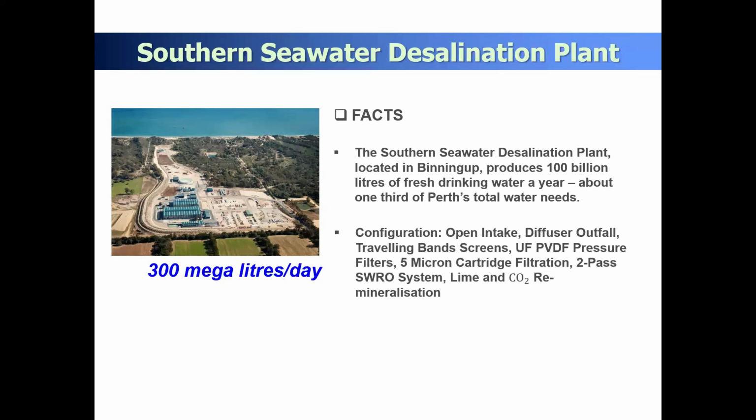Depending on what they like to do, they have different media, like natural sand, and even sand has different sizes, structures, and sources. Also, some people utilize activated carbon filters. So there are different ways of design, but in your assignment you don't have to go into that much detail about which kind of media filter you have. Just a media filter is a media filter, or ultrafiltration.